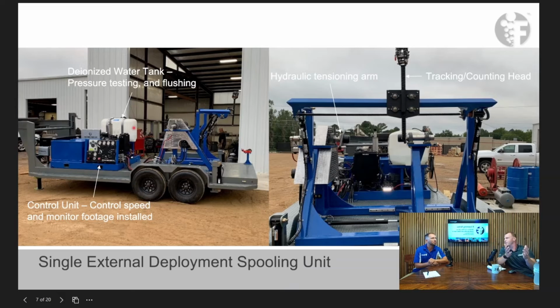Because when I think about typically production, 30 gallons is the best rule in the Permian. As long as he pumps at least 30 gallons, he's going to flush pretty much any string. How many feet is that? Usually right around 10,000, I believe. Perfect. Which is going to cover most of your Permian wells, right? But that's just a general rule.